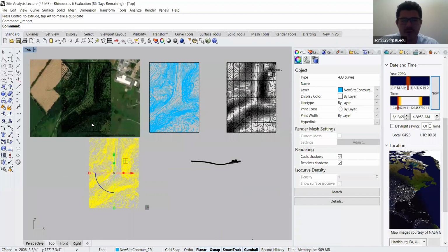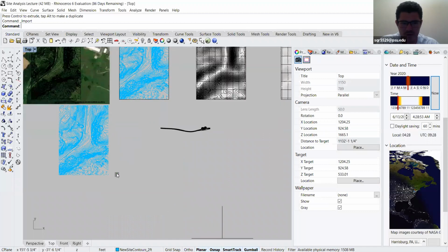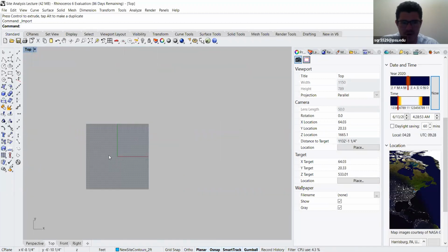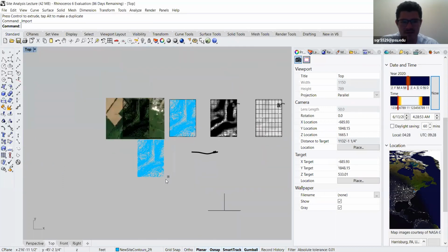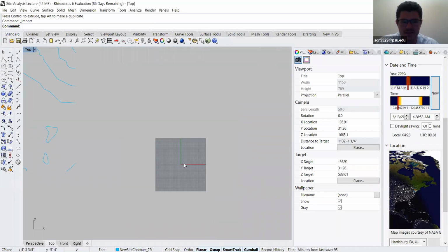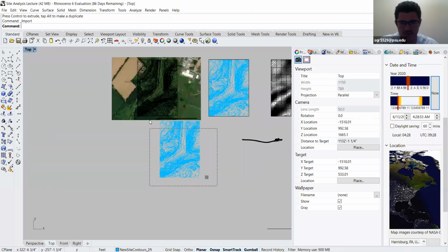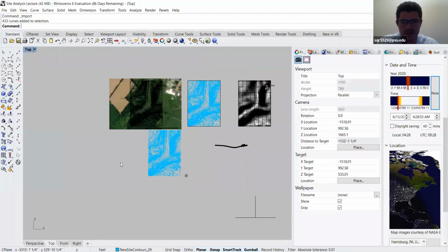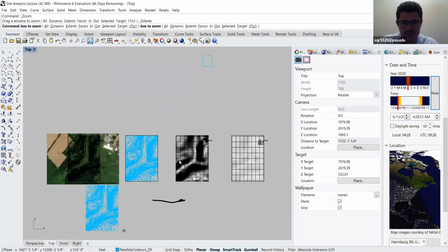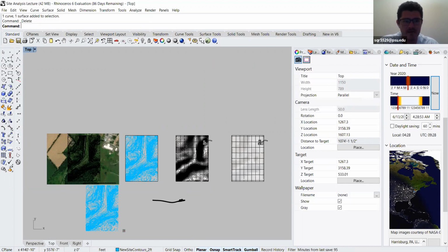Then you just bring it in. I try to work around the origin whenever I'm in Rhino, because when you bring files in and out, it's easier to find them. So I like to snap it. If you just do move and 0, 0, 0, and grab anything, it will automatically snap it to here. That way I don't have things floating out in the middle of nowhere in Rhino.